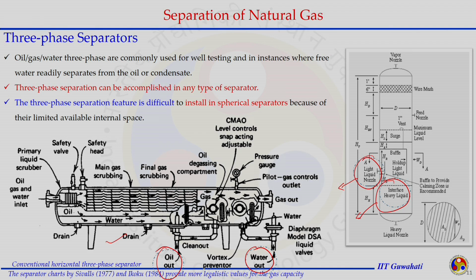So, there should not be any difficulty when we are dealing with a three-phase system. In fact, three-phase systems are important when we are performing some specific kind of test with the well, when we are sure a third phase will be present, like water also getting produced along with the gas and oil. In that case, we should go with a three-phase separator only.